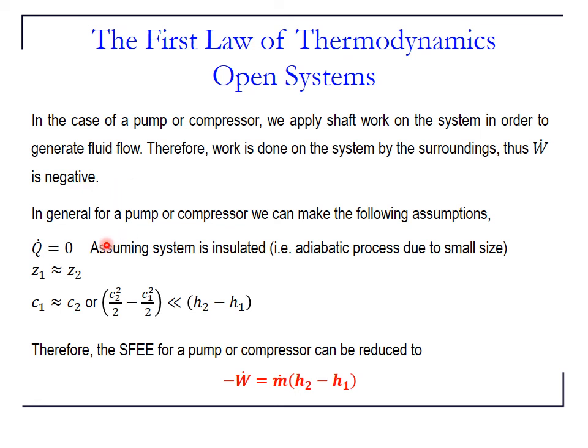In most cases, the size of the pump and the compressor is quite small, so it is practically quite easy to insulate, and we can consider the process adiabatic, so the heat transfer is zero. We can also ignore the potential energy change and the change in the kinetic energy, because its magnitude is much smaller than the change in the enthalpy.